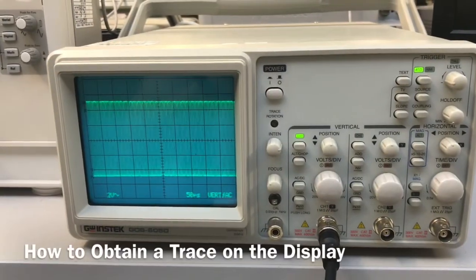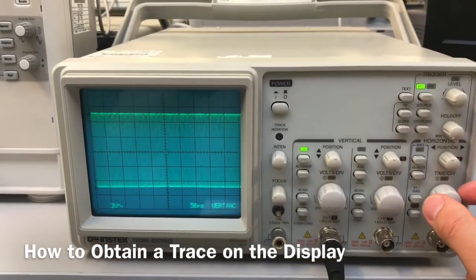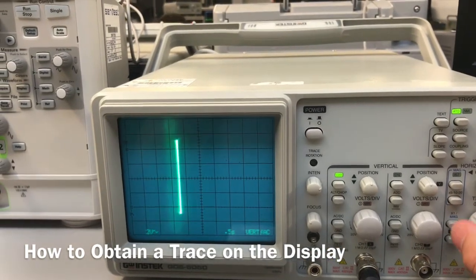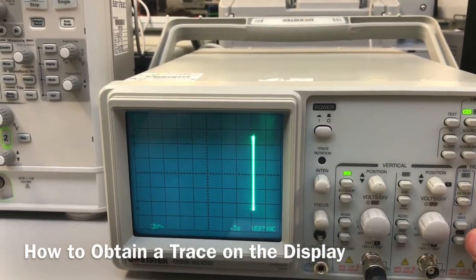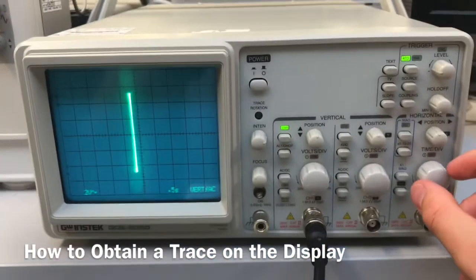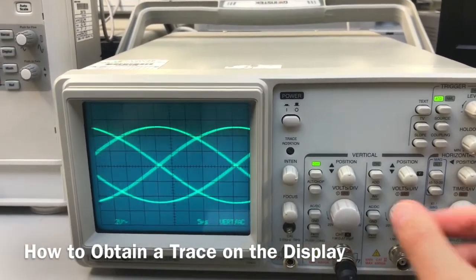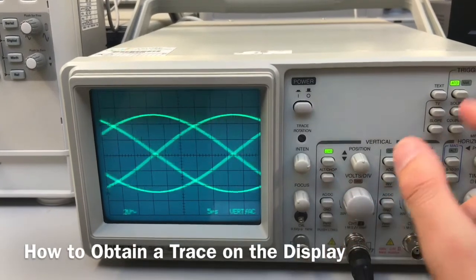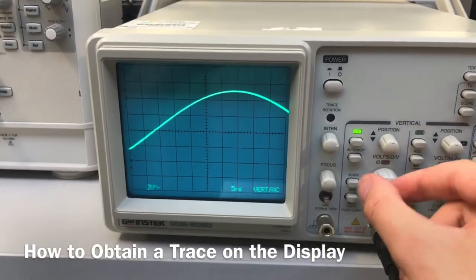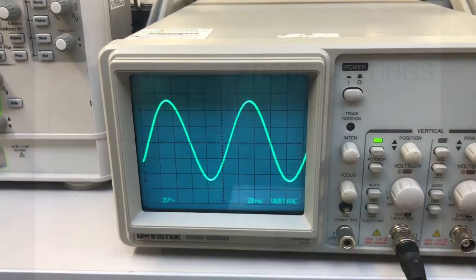So to display a signal, you would basically have to vary the time division and the volts per division. So here, obviously, you cannot see the signal; it's not displayed properly, as it should show a sine wave as it's connected to the signal generator. So basically, you will increase the time per division like this, and then trigger the signal, and just like that, and then the signal is displayed.